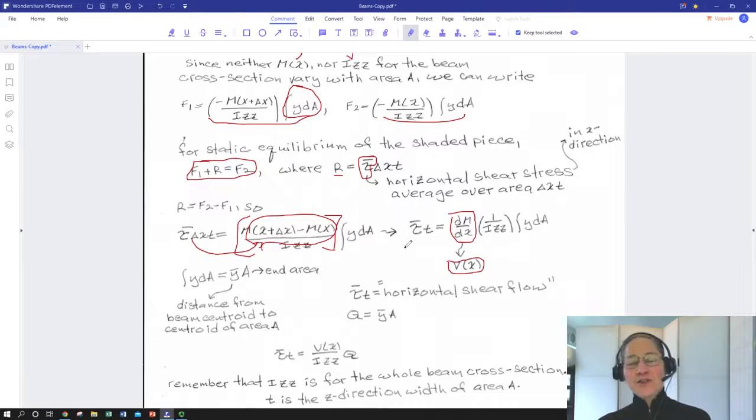So we're saying the shear stress, and I'm going to do a little impromptu box here just to remind us of which shears we're talking about, because this is where it's real easy to lose this argument. So we are relating the shear force, and of course I have to look inside my little box again. We're relating the average shear stress on that face times this thickness dimension on this end, to the shear force on the opposing face at 90 degrees.